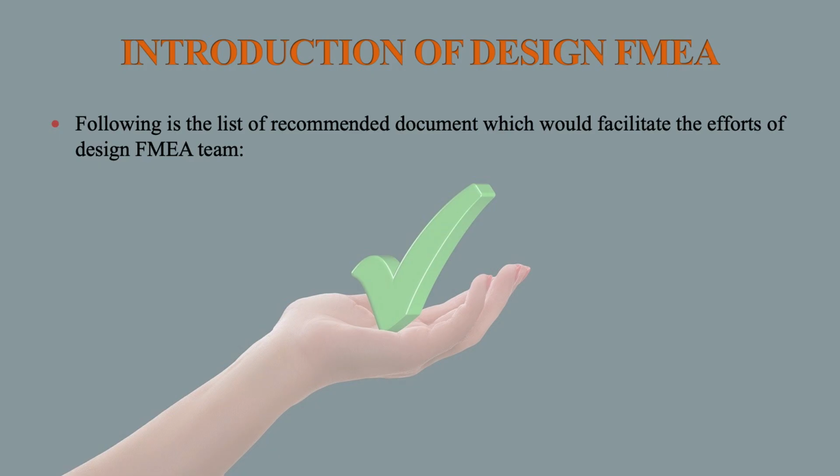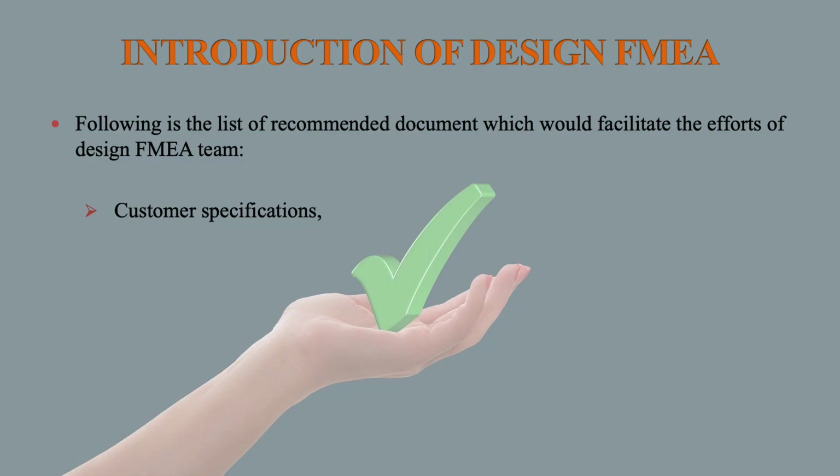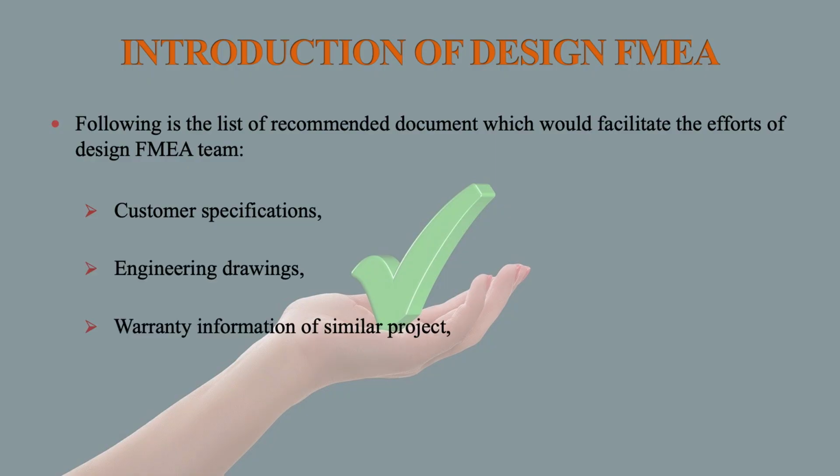The following is the list of recommended documents which would facilitate the efforts of the Design FMEA team. The team is constituted to conduct the FMEA. For them, there are various requirements like data requirements, data about customer specifications, engineering drawings, warranty information of similar products, or previously performed design FMEA on similar approaches.